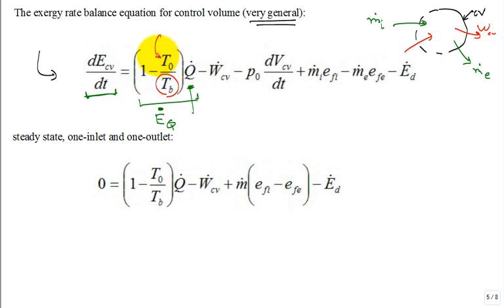Okay. And then the exergy can flow out with the organized energy transfer known as power. There's no factor here that's 100% times W dot. This in the parentheses is always less than 100%. It's some Carnot efficiency. Okay. What is this term?